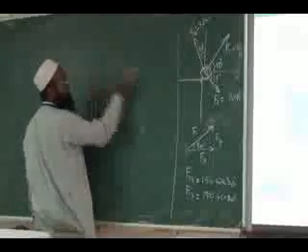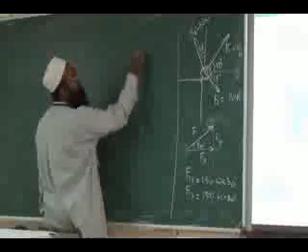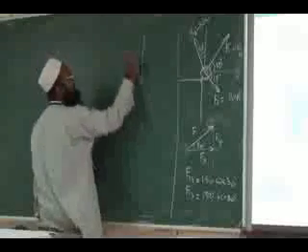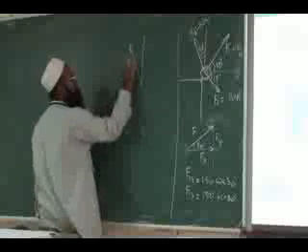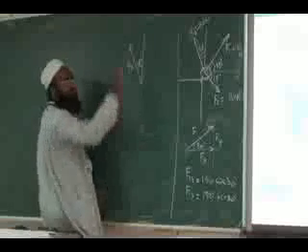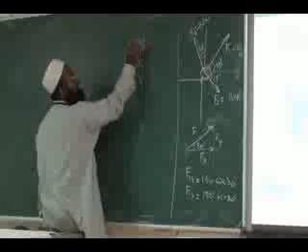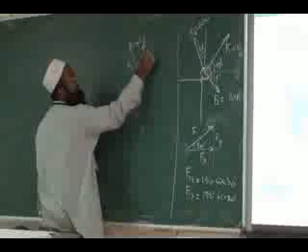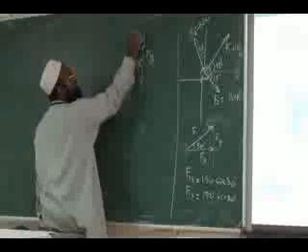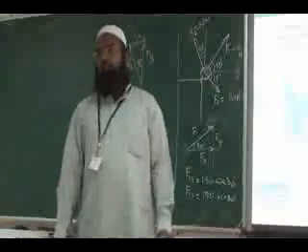If we consider F2, F2 is acting 20 degrees to vertical. I resolve into two components like this. This is your Fy, this is your Fx.